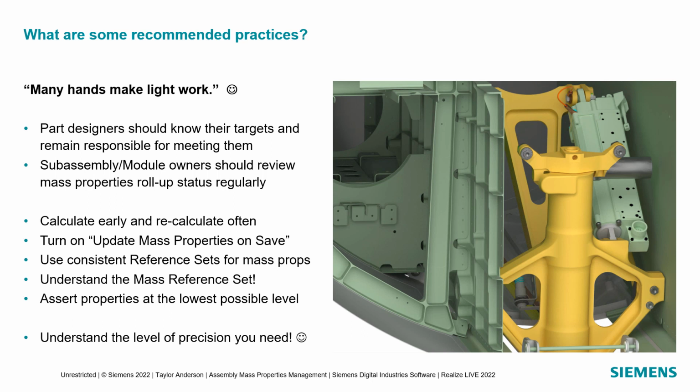There's a distinct usage of that reference set for mass properties, right? And this is more of a site setting, where you're going to be looking to the contents of a particular reference set for calculating mass properties, regardless of what's displayed at the moment, right? So a little distinct usage there. Showing and hiding things in the display should not be changing the mass properties, we think, and customers have agreed. And so that's a little important thing to understand relative to mass properties. And again, those two distinct usages.